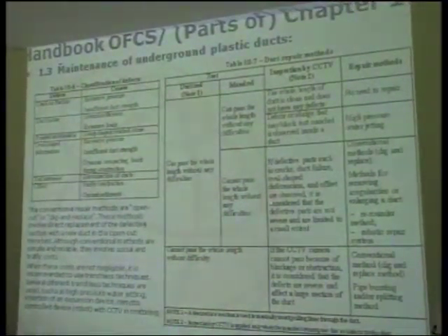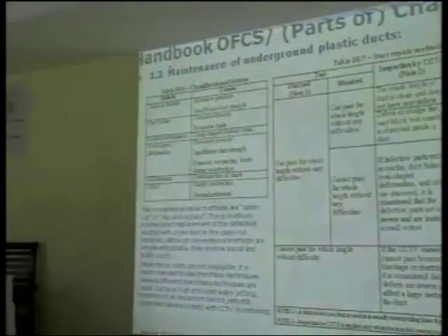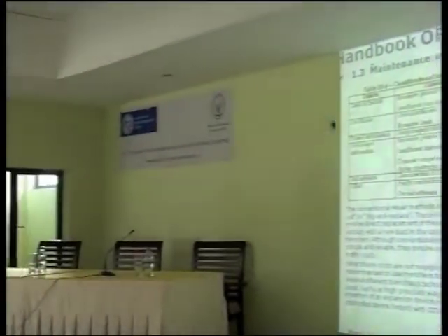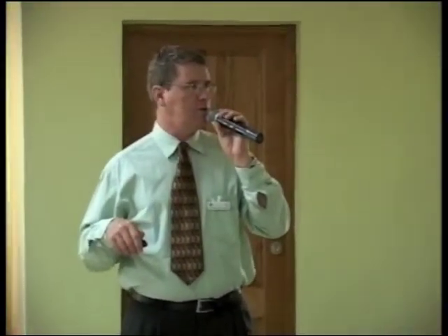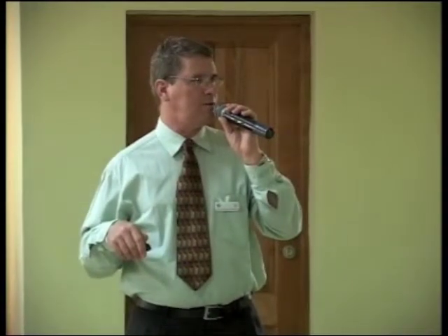If the defect is more related to ductile failure or cracks or deformation, there are some options. One is dig and replace. Another is the use of instruments to just repair the damaged section. And the inspection with a camera most of the time allows more detail and helps a lot to choose what could be the alternative to be used.